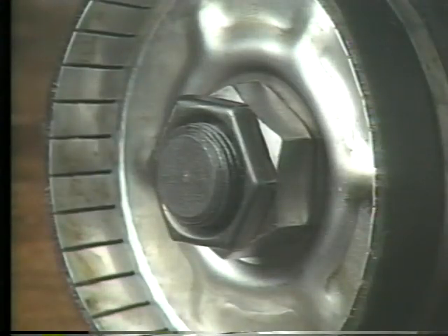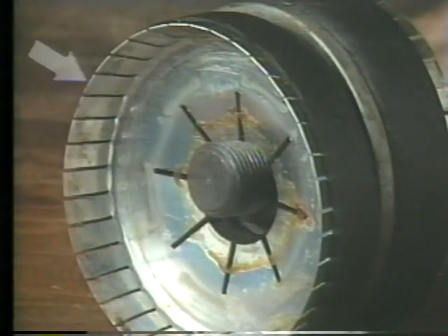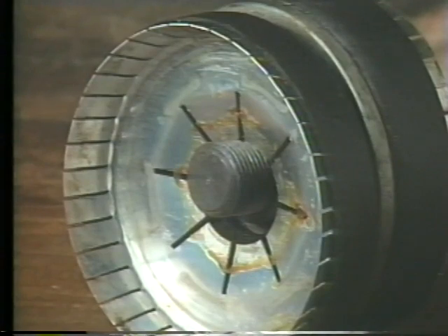Each subassembly is comprised of essentially the same parts: a rigid metal disc called a flange that strengthens and supports the cup packing spring, which is a flexible slotted metal cup used as a form for the cup packing. It pushes the cup packing against the walls of the cylinder so that it forms an airtight seal that prevents air from leaking between the piston assembly and the cylinder wall.